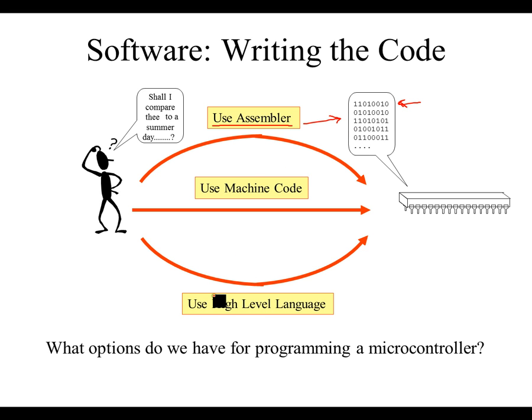You can also use a high-level language like C. When you use assembly, you still have to know the hardware, the internal workings of the microprocessor, because you're setting bits and moving bytes of data, so you're doing very rudimentary tasks. In C, you're doing things like if statements, if this then that, while statements, or for loops.